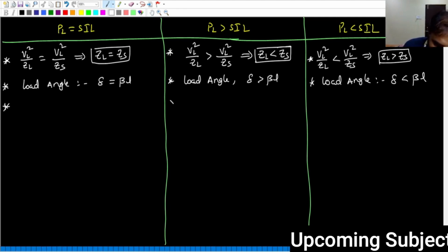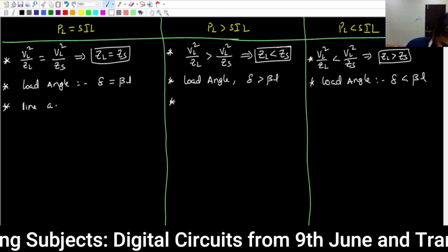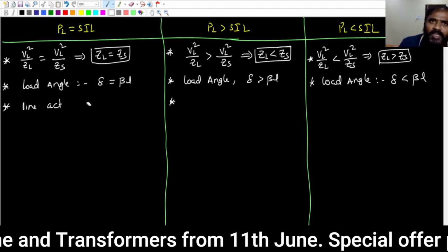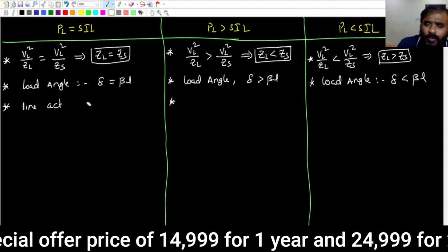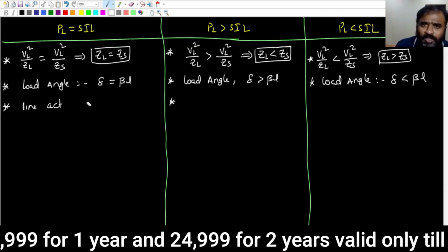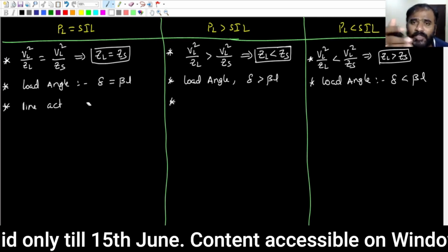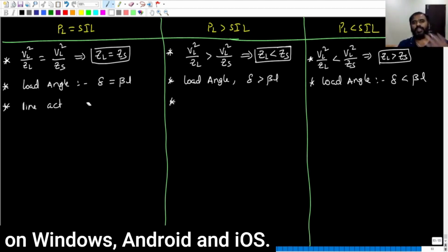So to get clarity, tell me, here the line acts as neither sink nor source for reactive power, because reactive power generation and consumption are the same. The transmission line generates reactive power because of its capacitive nature, and consumes reactive power because of its series inductance. So finally, reactive power consumption and generation are the same.